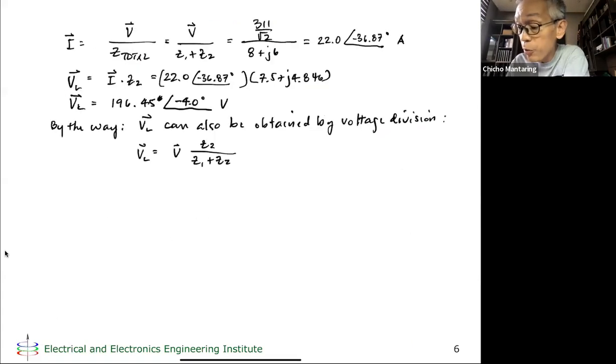So my complex power S is now just equal to my voltage multiplied by the conjugate of my current. The conjugate is the mirror image of your phasor, mirrored along the horizontal axis. So what does that mean?